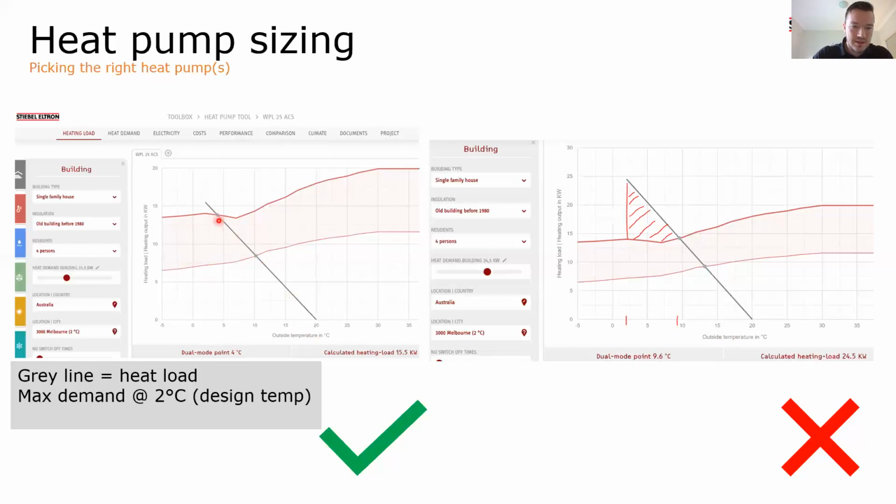So there's a little bit here, which is going to be effectively maybe 1% throughout the year in terms of complete demand needed, that we cannot cover with the compressor. And at that point, we would need a second heat generator or a second heat source to kick in to help. That's hence the bivalence point. But this is still a very good design, hence the tick here.